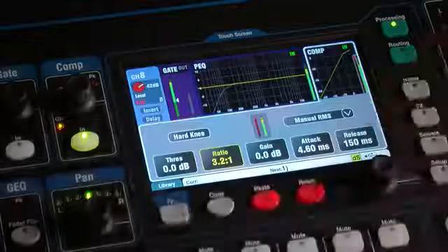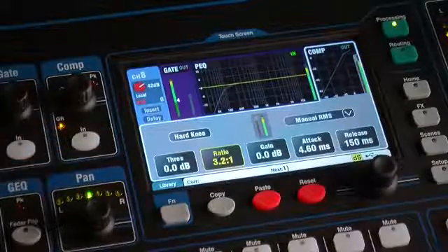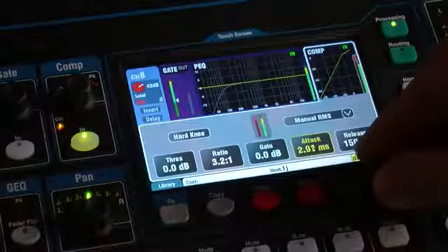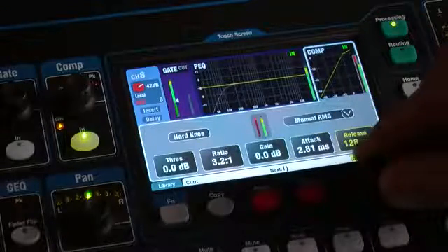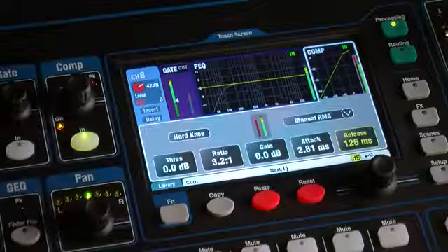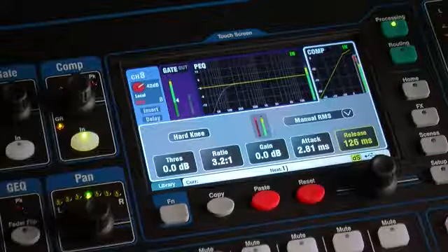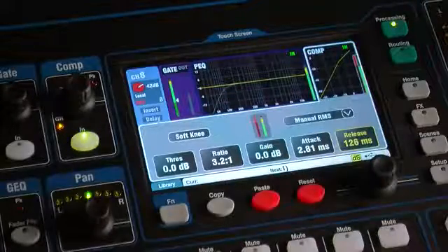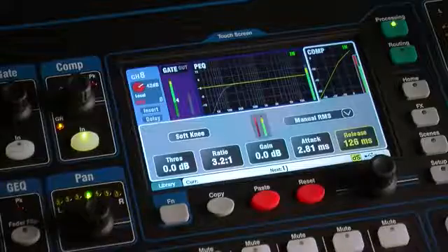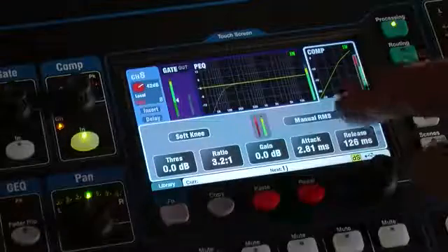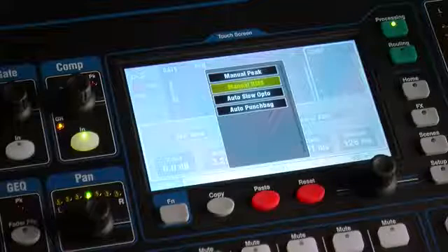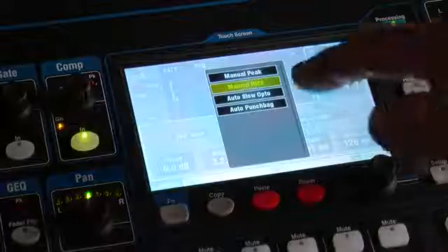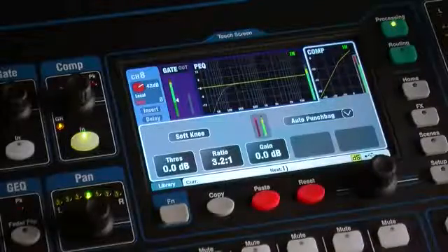Toggle the compressor in and out and turn up the gain so that the average volume is similar. Adjust the attack and release, for example, to achieve a punchy dynamic sound or to smooth out the response. 2 knee settings are available. Soft knee means that compression ratios increase gradually from 1:1 to the set ratio as the signal approaches the threshold. 4 compressor types are available using the drop-down menu. 2 manual types allow user control of attack and release. 2 auto types provide automatic control of the compressor dynamics.